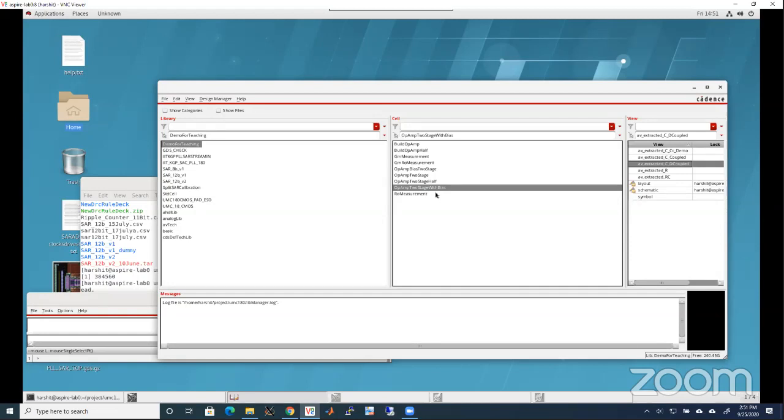Okay, why not use always RC? Yes you could, but the problem is that your netlist size is so big that it takes a long time to simulate. But I want to see whether current is flowing properly or not. How much is the drop in the wire, voltage drop in the wire? For that, why do I need to do an RC extraction? An R only extraction will do that purpose, right? So it all depends on. Now if I have a very low frequency circuit, right, biomedical circuit, why do I need to do an RC extraction? A C only extraction is good enough. So these are some judgment calls that a designer makes based on what is the design spec.